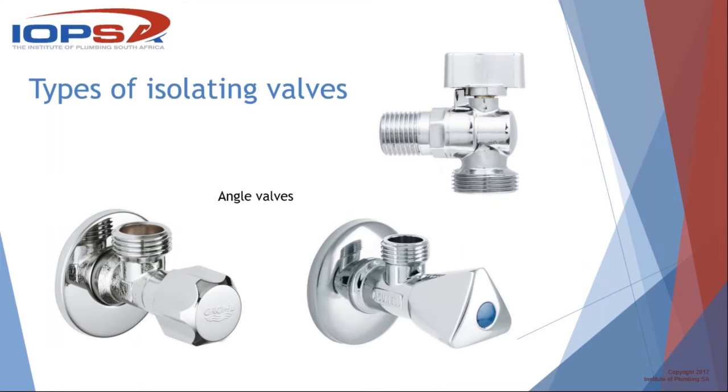Butterfly valve, obviously that's for larger installations, which is not common in domestic, but a lot of complex supplies will have butterfly valves in them. And then a gate valve that can be shut off quickly. This can't. A stopcock can't be shut off quickly. Same applies to angle valves. So between a stopcock, gate valve, lever ball valve, and angle valve, that's pretty much the scope of the shutoffs or isolators that we're going to use in a domestic situation.